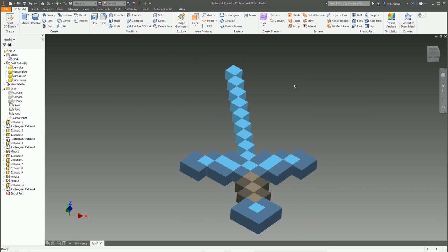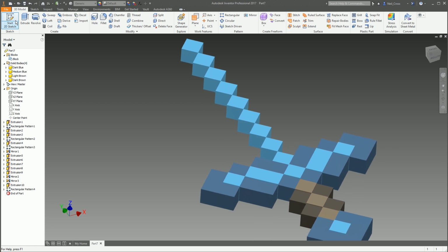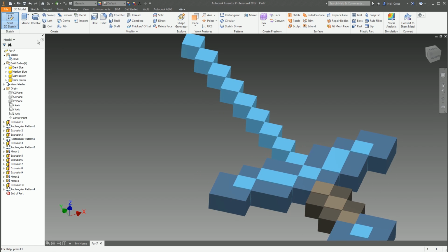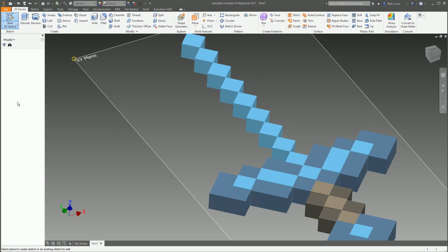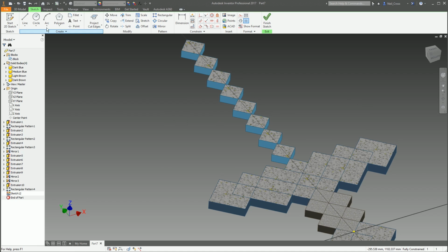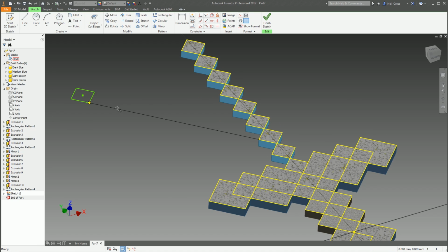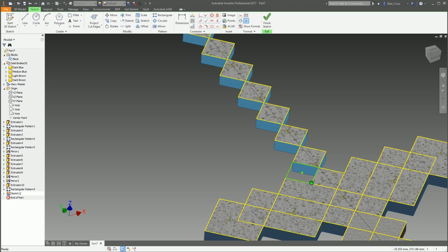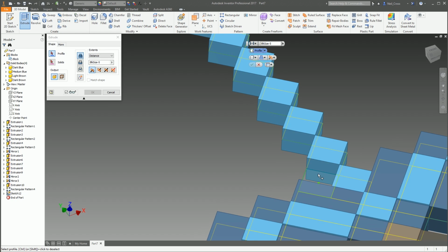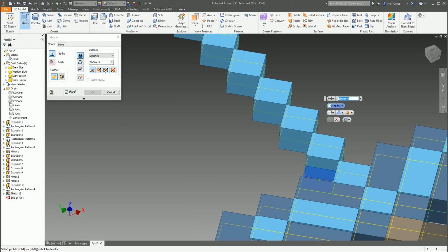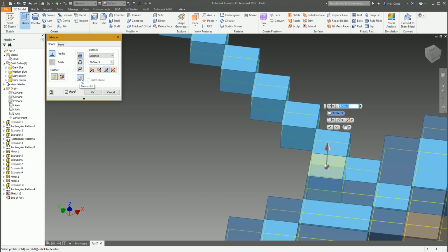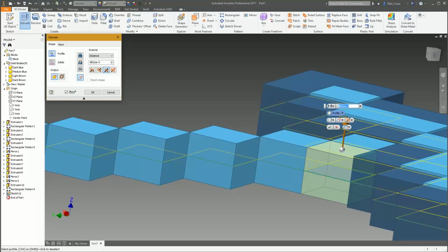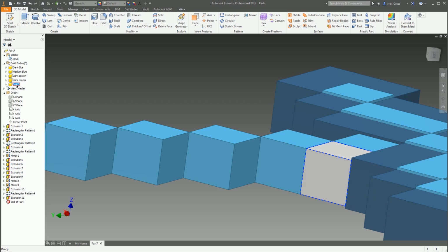Got it. Okay. Right, so now we need to create the new block. So this is the light blue block. So we're going to sketch on XY again. And then project edges, and then place the block. And then this one goes in there, doesn't it? Yes, this one goes in here. And then extrude that. Right, so this is a new solid, so we're going to click that new solid button there. So this is going to be light blue. It's sort of flush with the rest of the blade. So let's just OK on that, and then we're going to name this one light blue.